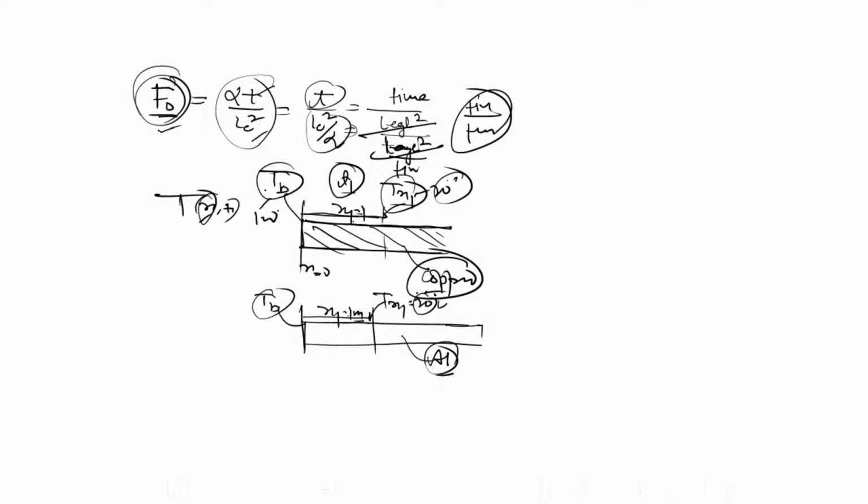Try to understand, a rod is there, one rod is copper, other rod is aluminium. And the question is that at some certain distance, in time t1, temperature is found to be 20 degrees Celsius in the copper rod. At the same distance in the aluminium, to find the same temperature of 20 degrees Celsius, how much time will it take? As far as common sense is concerned, copper has more thermal conductivity as compared to aluminium. Then obviously aluminium will take more time to reach the same temperature of 20 degrees Celsius.